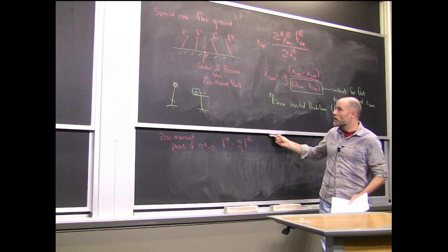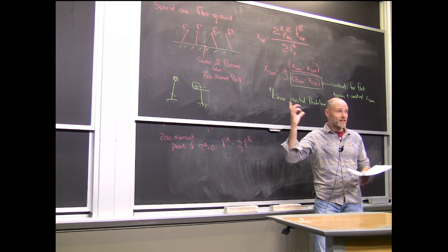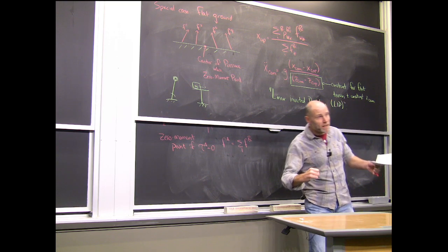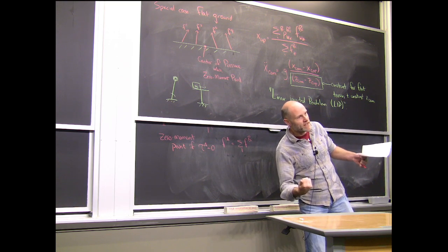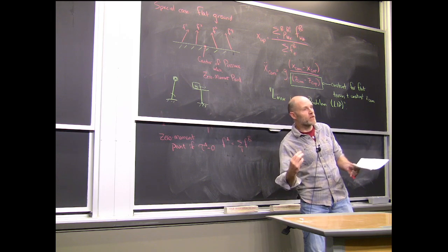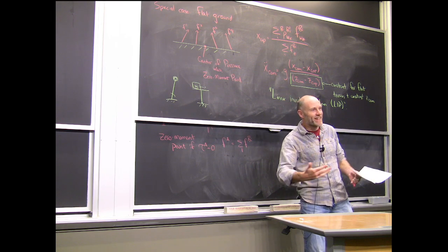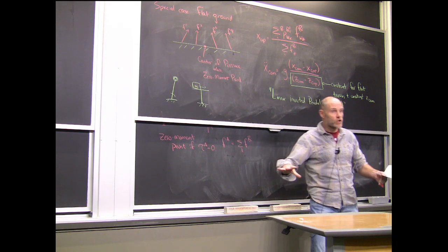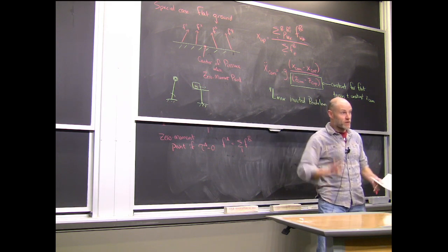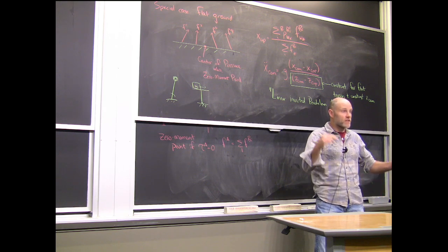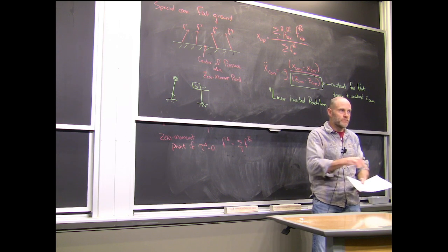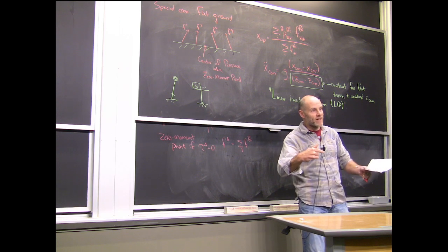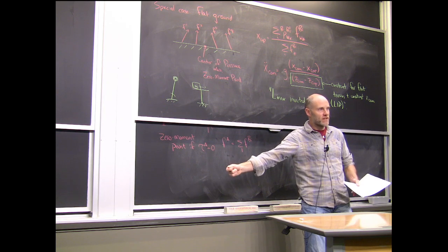The zero moment point, since it is the center of pressure, is also inside that convex hull, okay? But when you're actively tipping over your contact, then they can differ, because you have a moment. The place where you would need to have zero moment could be outside. But as long as you are not tipping over your foot, so you have the foot flat on the ground, for instance, then the zero moment point equals the center of pressure. It's only when you have a moment that the center of pressure is stuck inside the support polygon and the zero moment point is outside.